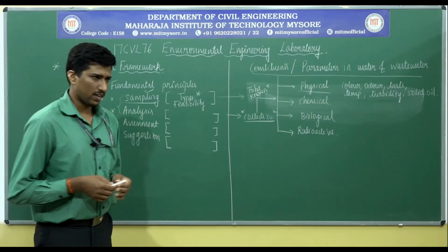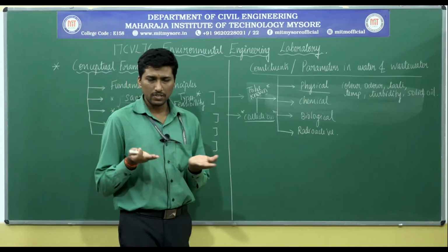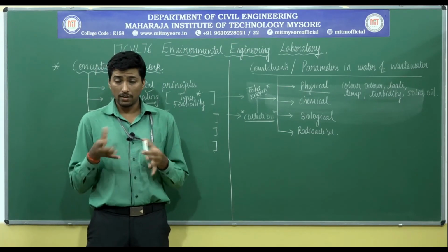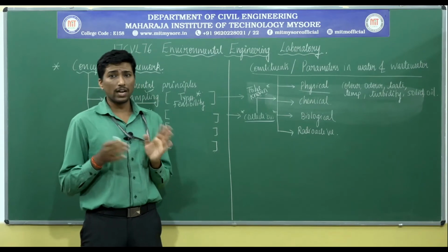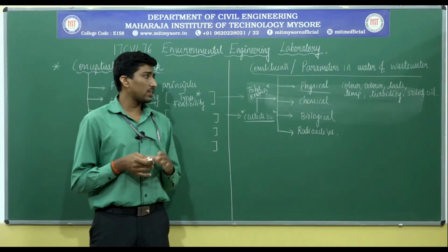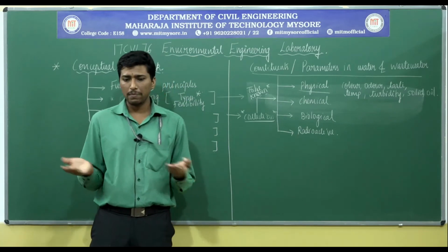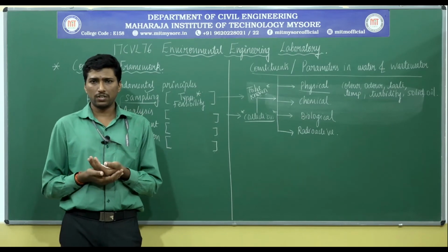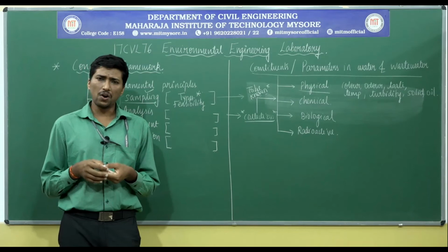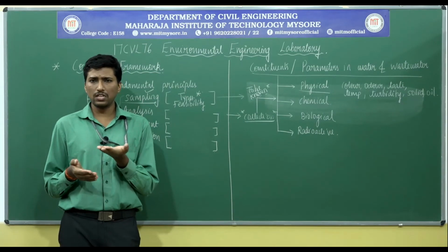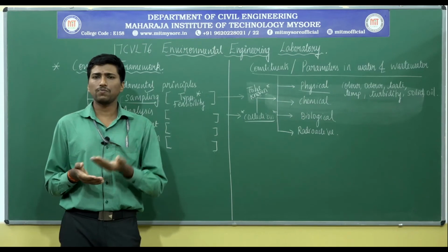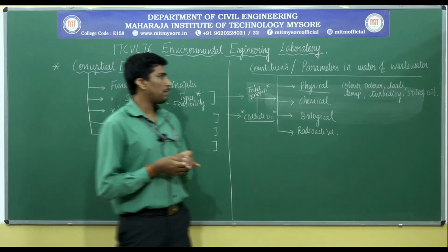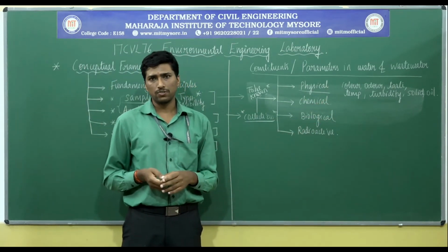Solids can also be categorized as suspended solids, which are suspended in nature, and dissolved solids, which are dissolved in nature and cannot be identified visibly, so you need to analyze them. What kind of analysis will I take up? Next thing you come across is the oil content. Based upon the separation or density, you can see the oil floating over the water. Maybe the spillage of oil or grease, you can see it tending to travel across the surface of the water itself, or it has been retained. How are you going to remove it? So these are all the critical parameters which have importance.